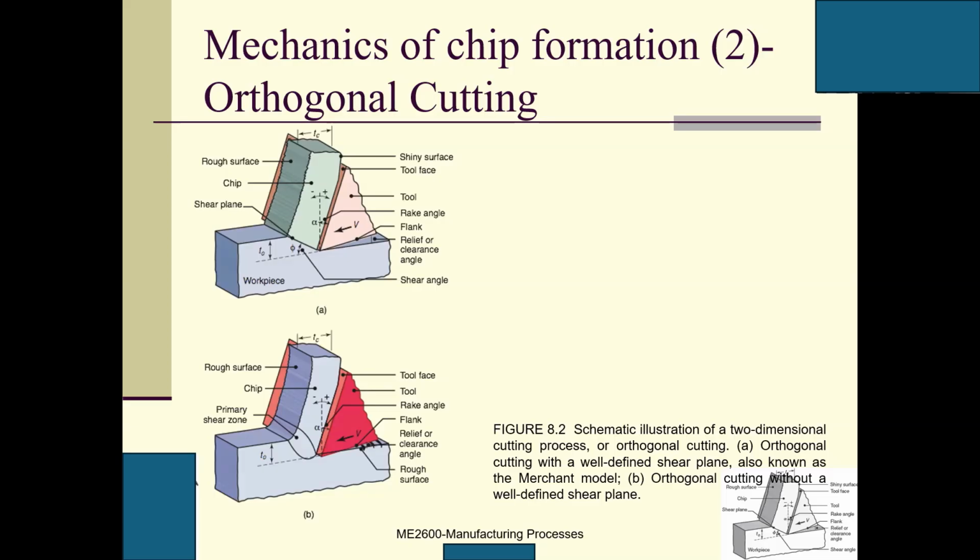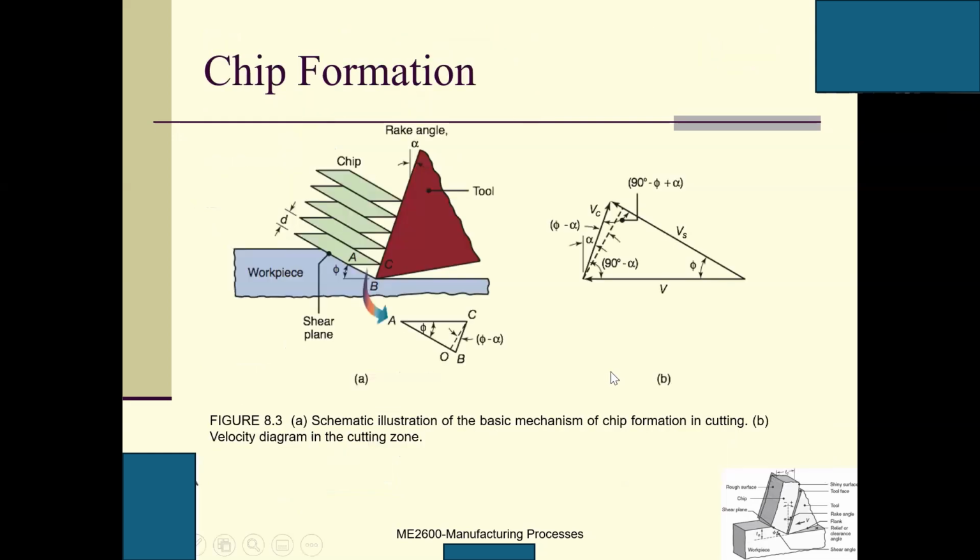What do we call this angle, guys? Here, what do we call? Yeah, here. This is shear angle. Okay, shear angle is a very important one. And we will use shear angle to calculate the cutting forces and energy consumption, a lot of those things. We need to use shear angle.